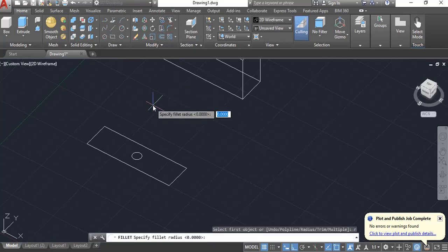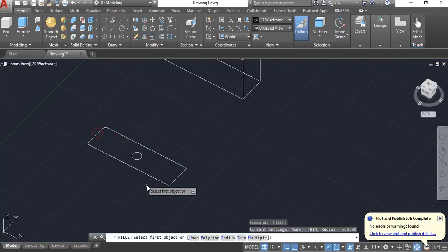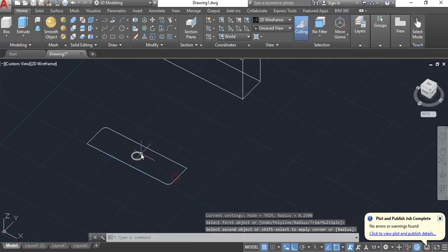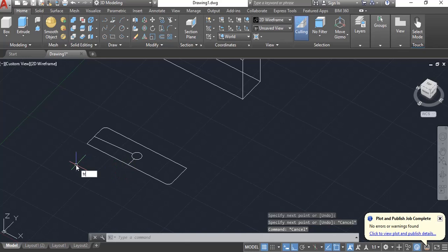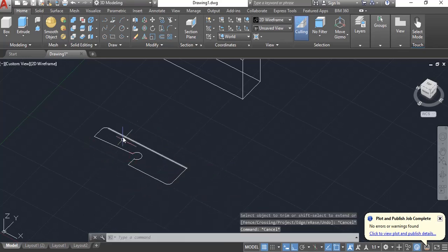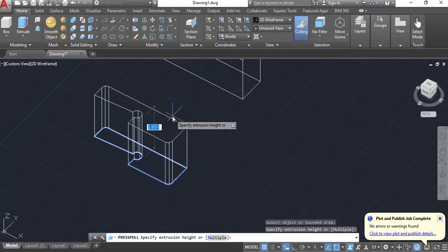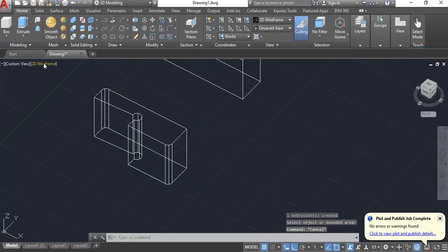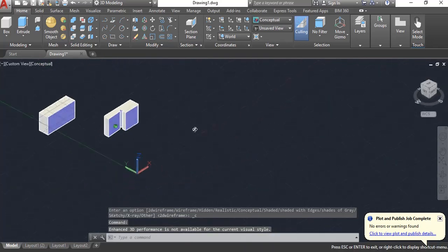So we'll set the radius, R for radius, and let's say it's a 1/4 inch. And we could do a radius edge here and over here. And we could do some sort of line cutout, let's say midpoint to the quadrant and quadrant to midpoint here. And let's say we're going to trim these line segments out here, here, and here. We could do something in a 2D flat pattern, and then press pull this up into a 3D solid. And once again, it makes them into that 3D solid figure.